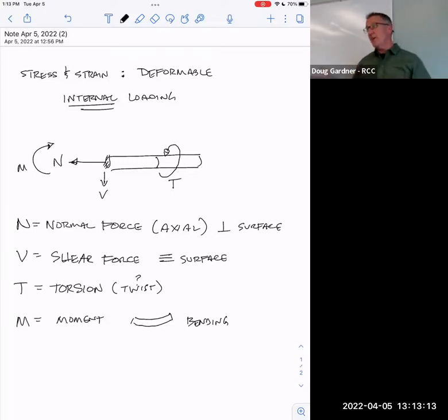But you can appreciate in a car, isn't the twist a huge part of that? You've got an engine firing, and it's basically creating twist that you transfer to the back wheels. And there is a U-joint in the car. I don't know if you know this or not. There's a U-joint in the car designed into it to actually snap so that something more important doesn't break. There's weaknesses built into all kinds of things, so that if you ask your wheels to do too much work by peeling out, so to speak, it doesn't break the engine.